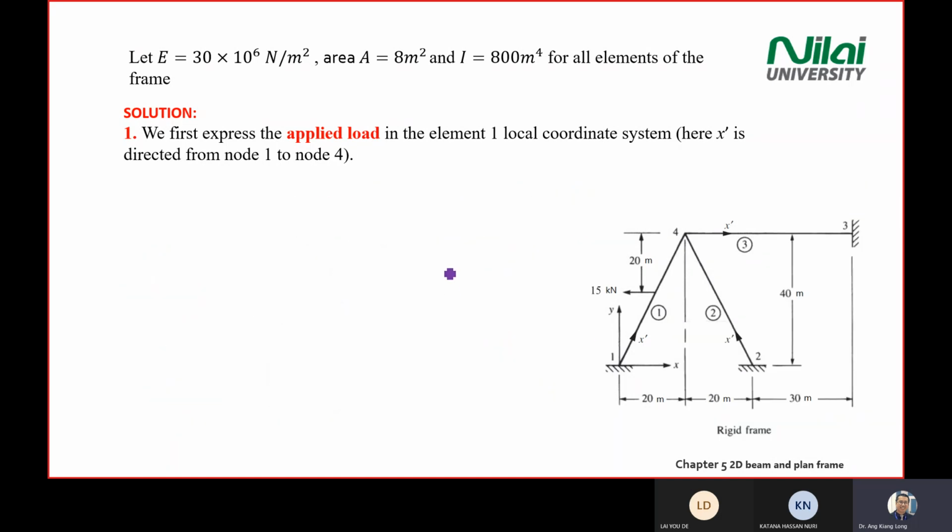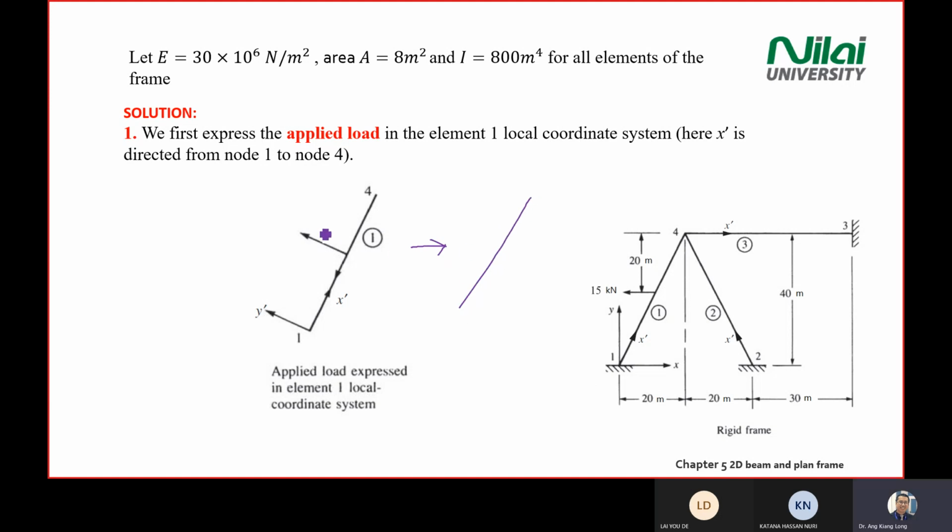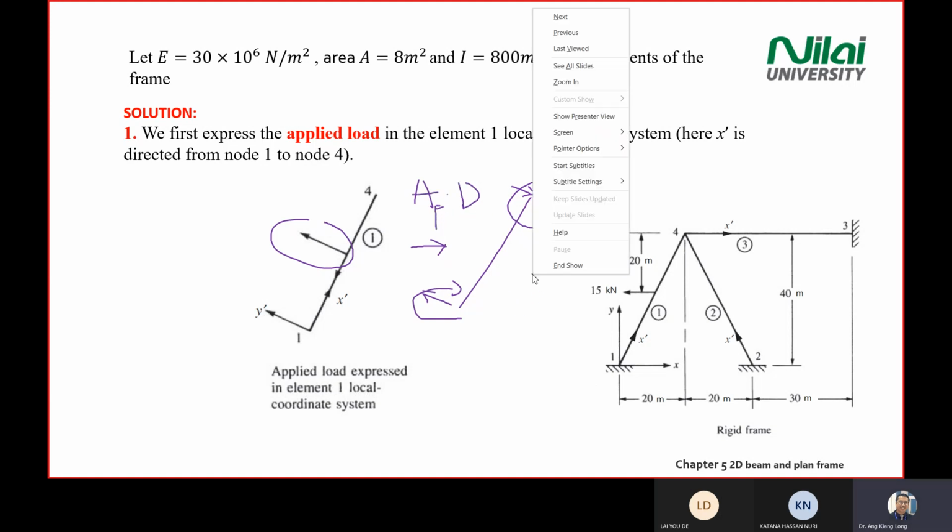So after that, you convert these forces, because this is a force at the middle. And if you look at Appendix D, there's one case where we can convert this force into this one and this one, and maybe there's some moment at the side. It can convert these forces to forces at point 1 and the other end, and a moment, by using Appendix D. Appendix D. Okay. All right.